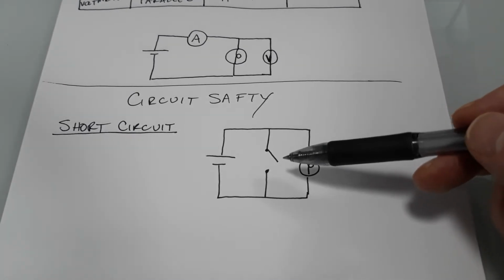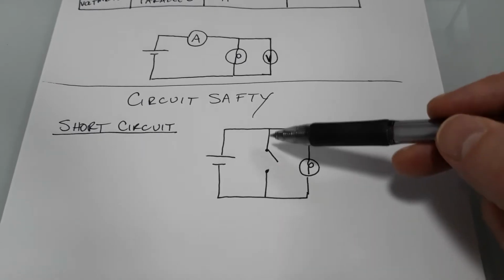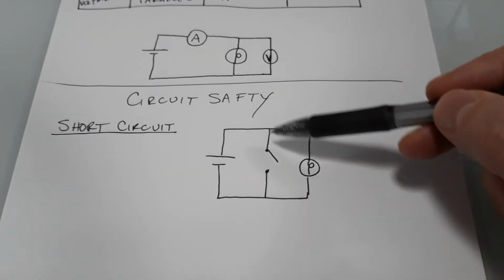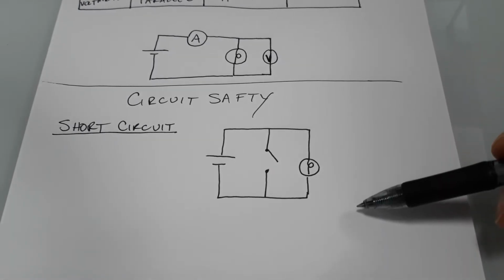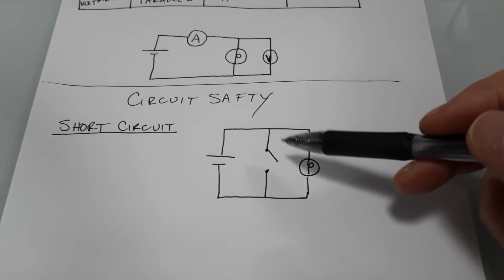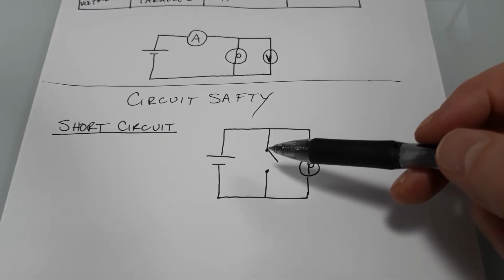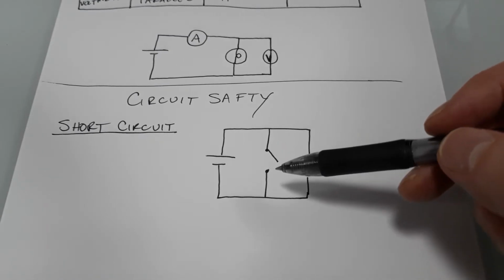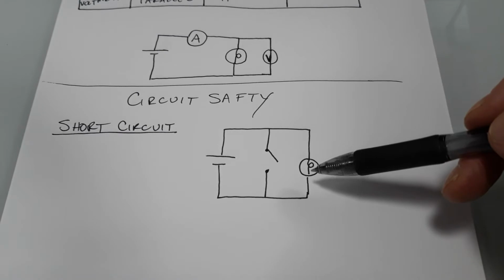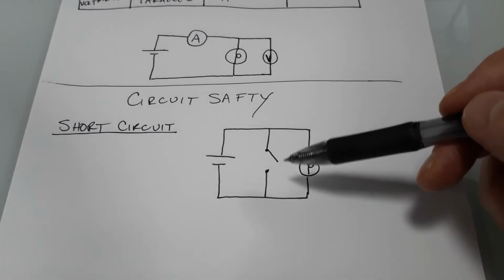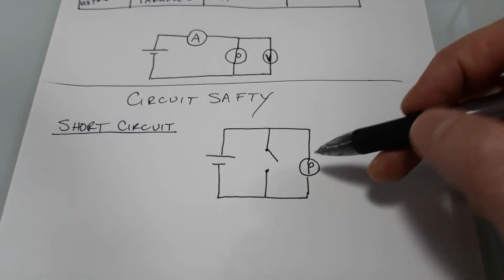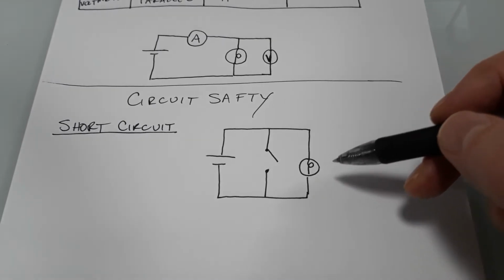But it's actually much worse than that. This short circuit, right? And, look, it physically is shorter because of where I drew it. But I could have put that switch over here on this side. Okay, so the word short doesn't necessarily mean that the path is shorter. It simply means that you're giving an alternate path that's going to allow it to skip one of the elements in the circuit, and therefore that circuit element is probably going to stop working because it's going to receive so little current that it can't function correctly anymore. And that is certainly the way that the light bulb is going to work.